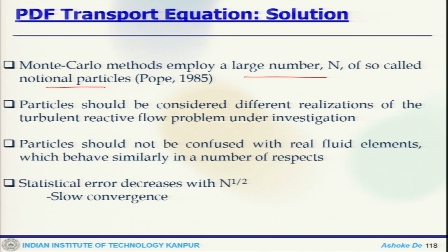So far, our discussion of the PDF transport equation has been in physical space in the Eulerian framework. Now, when you try to solve this particular equation, we are moving to a situation where we are introducing particles.